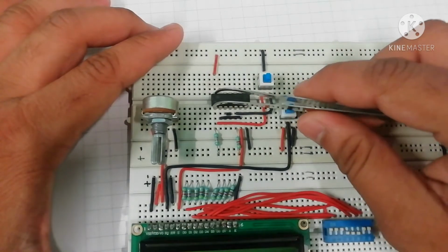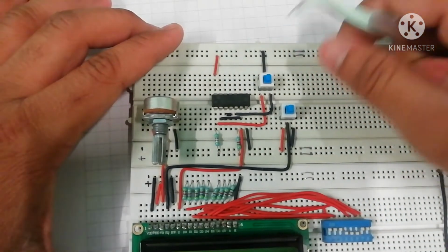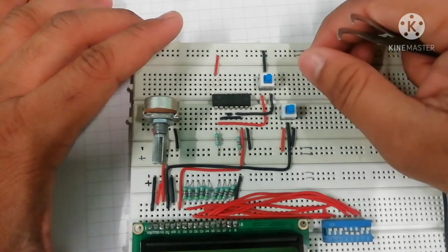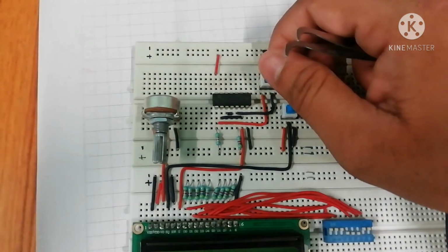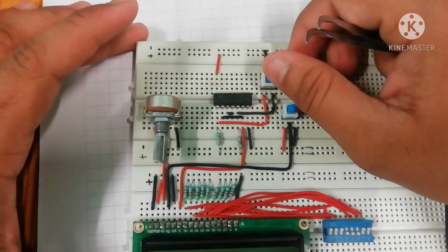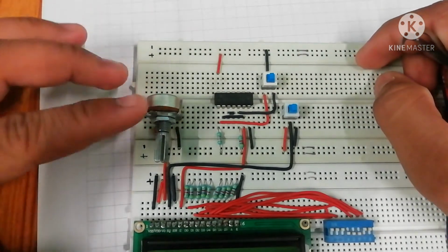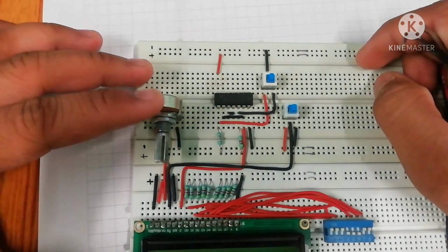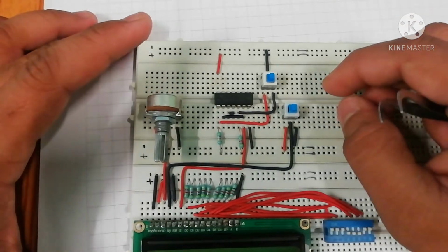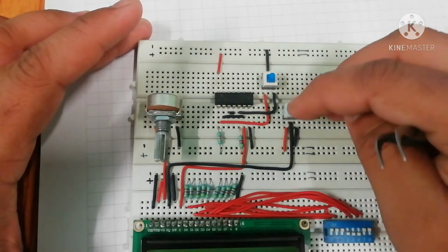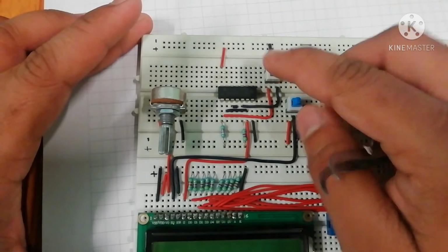The reason I have implemented a latch is that mechanical switches have bouncing problems, which means even if I push the button once, owing to the bouncing phenomenon, the enable signal is interpreted several times, which results in multiple commands. And on the left side we have the contrast adjustment potentiometer, and on the right side of the latch we have these two switches. One of these switches is connected to the register select pin, and the other switch is connected to the input of this latch.